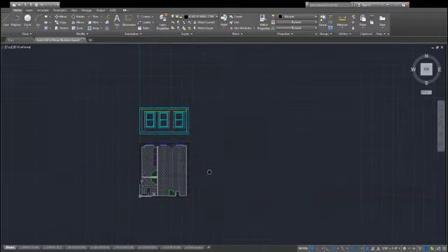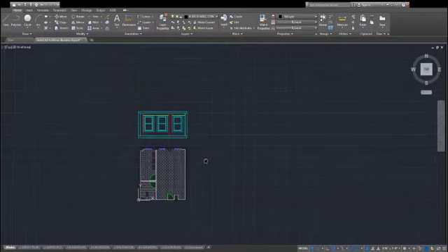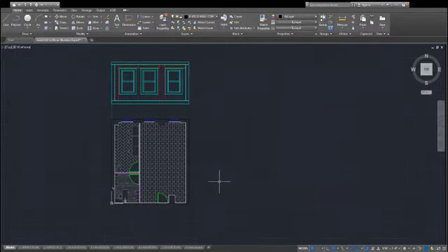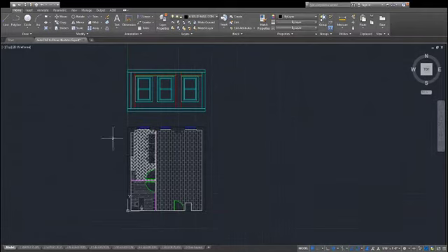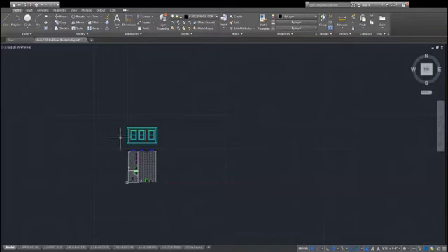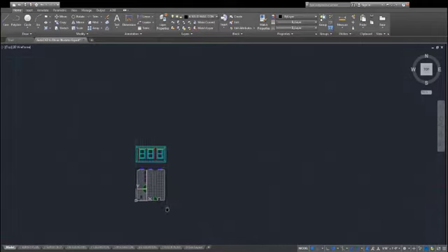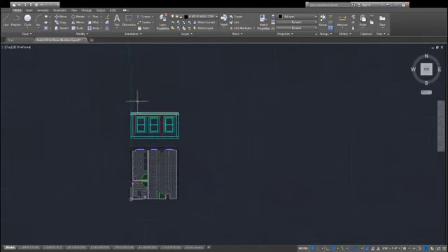Hello class. So today we went over how to import, export, and work with our AutoCAD files in other different and separate programs. One of the foremost things you want to make sure of is that the AutoCAD drawings you're trying to export lie within the proper XY coordinates, because AutoCAD works within sort of an infinite range of space and other programs do not. You have to make sure that the portion of the drawings you would like to export and work with in other programs are within the maximum limit of where it can be shown.